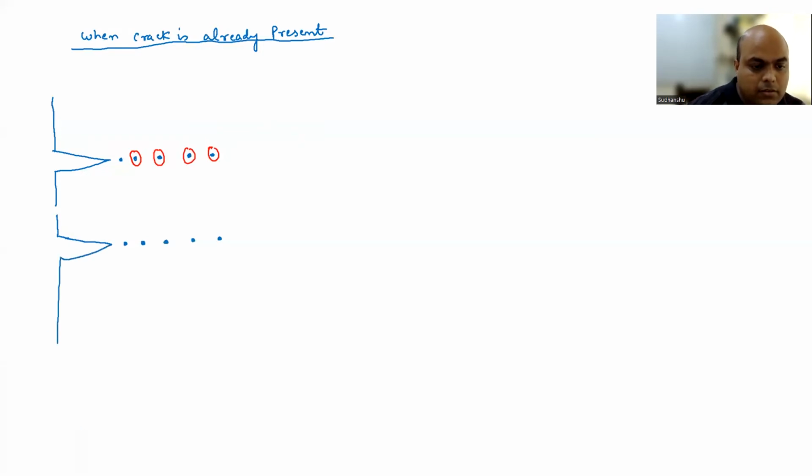So you're going to now nucleate, and then they are going to grow. This will lead to something like this. Say void 1, void 2 are like this. Okay, so this is like nucleation and then growth. So you have formed the void, they are going to grow, and the void which is very near to the crack, they are going to merge with the crack, and this is how your crack is going to propagate.